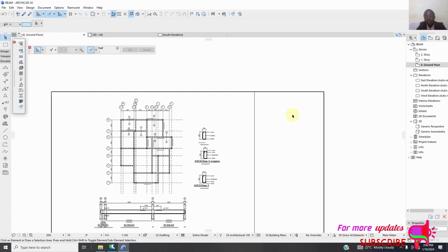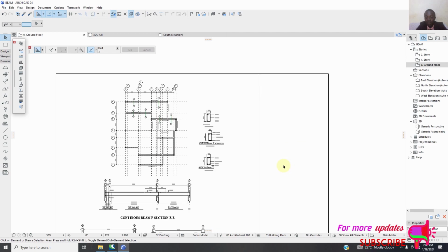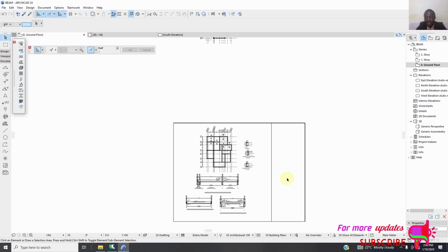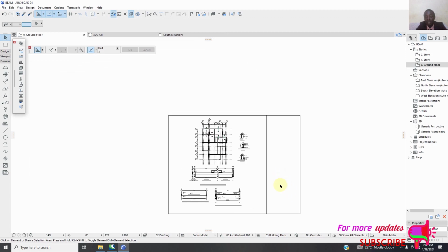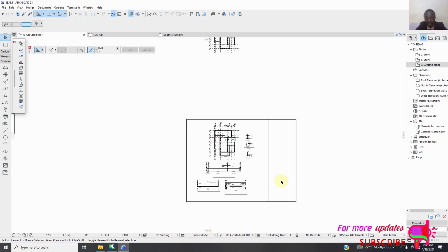Maybe all the drawings are in millimeters, unless otherwise stated. All the details, or the class of concrete is class 25 or class 20, the ratio and such stuff, the notes here. Then you go to the number of divisions down. Then you go to the project name, the client, and the company, and the one who drew it, the checked by, and such stuff.